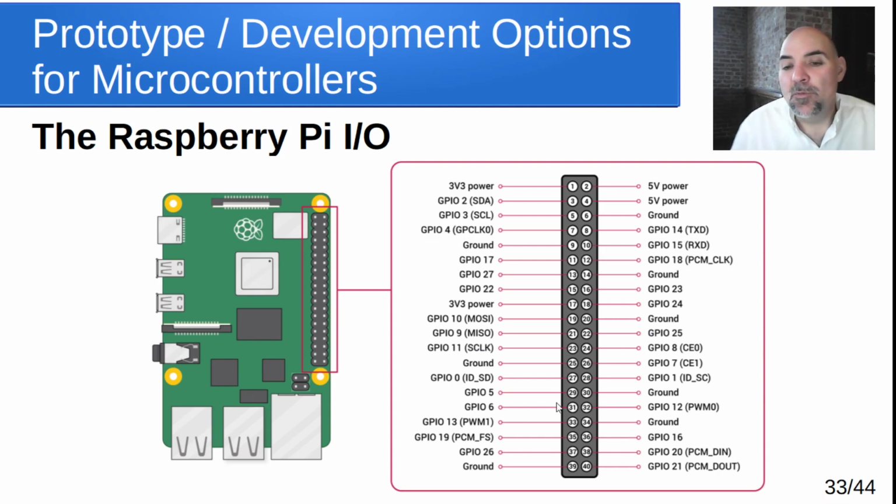One thing that is notably missing from this is A to D conversion. There is no A to D converter built in, but there are I2C or SPI A to D converters, so you could really just connect them to here or here and talk to them through that.